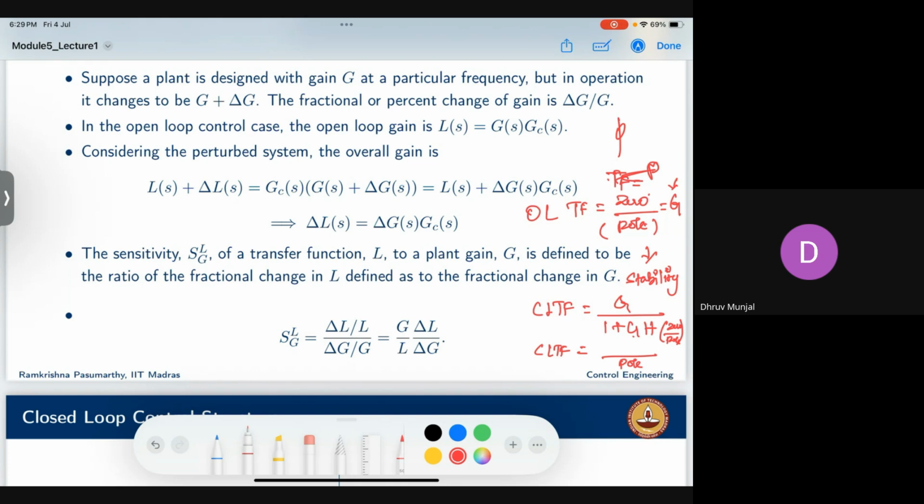Another point I want to make is if you consider a closed loop transfer function itself, where the zero is in the right half of the S-plane and your pole is in the left half of the S-plane. Here, if your pole is in the left half, it won't affect your stability. Your system is inherently stable. We are not going to consider the zero for stability.